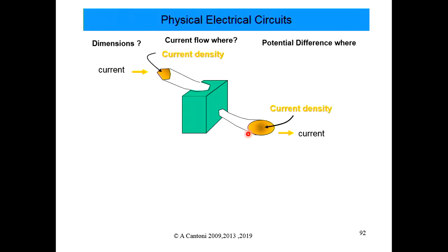And where there's a current flow, you have certain current densities, and actual resistance will depend on the frequency as well. Because we'll see later in EMT that you have the skin effect, where for higher frequencies the actual cross-section of this wire looks less. You may have potential differences in the actual wire.